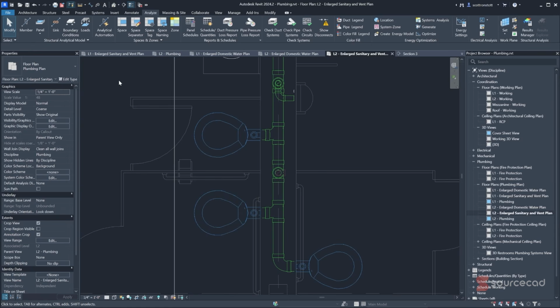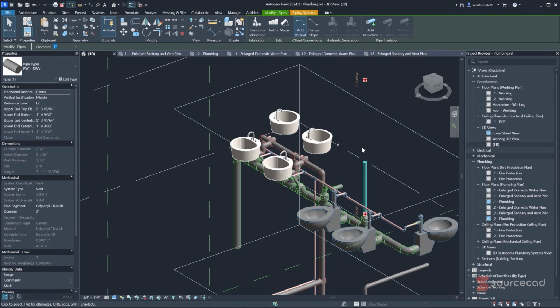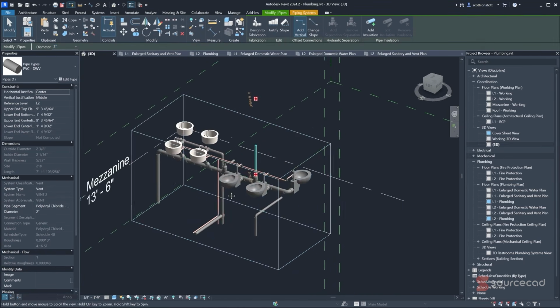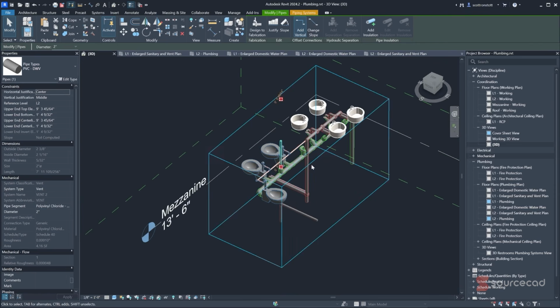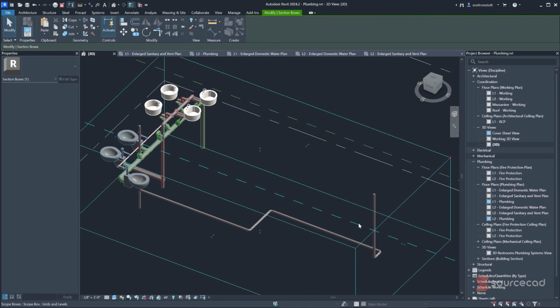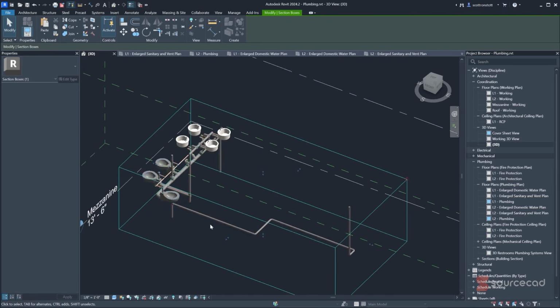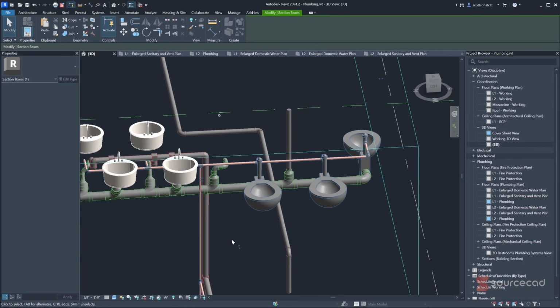So let's take a look at this in 3D. Where's my 3D view here? So we have a vent here on level 2 that's just going nowhere. And we have a vent below coming up. We want to join these together ultimately. Where does this go? This vent gets routed in the chase by the elevator core, I believe. But I just want to interconnect these vents. We can't have this turn upside down or else the septic would go down the vent. That's not going to work.